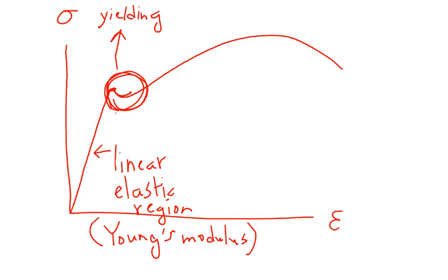The point where yielding begins, or the stress at where yielding begins, is what we call the yield point. And the yield point, theoretically, is where the linear portion ends, right? But that's very hard to determine. If you blow up that region again and start looking, you have this linear region, this straight line, and then it starts to deviate more and more from that straight line.